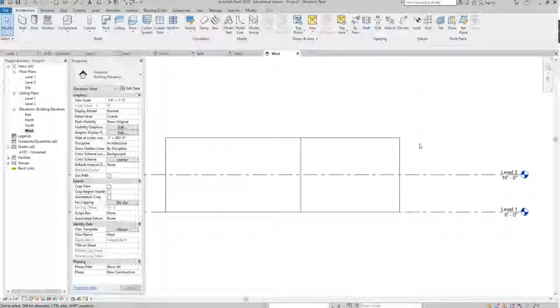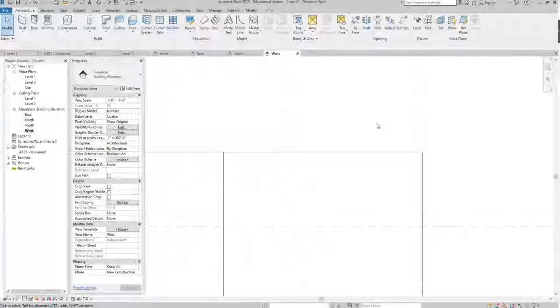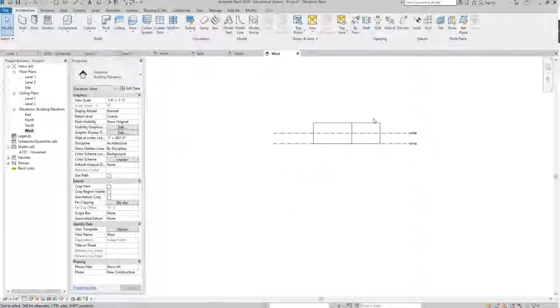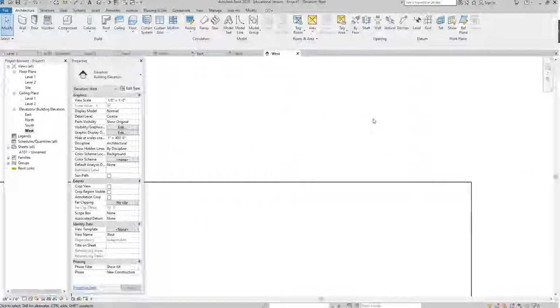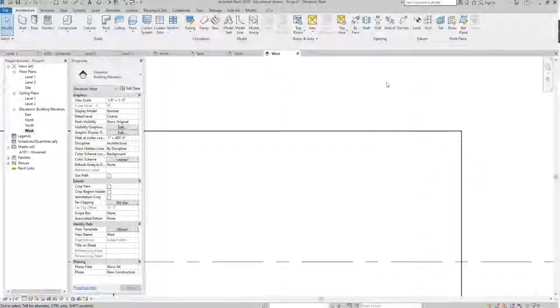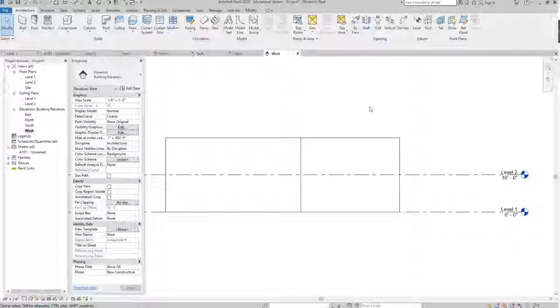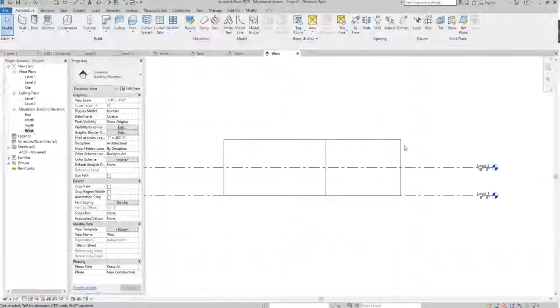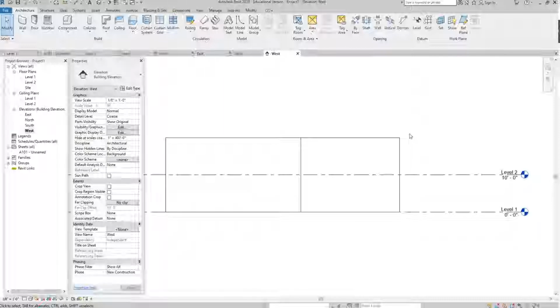So if I want to zoom in Revit, on my mouse, I have a little roller button, right? And if I hover over this white space and I roll my mouse away from me, I zoom in. And if I roll my mouse towards me, the little roller, I zoom out. Okay, so I zoom in, I zoom out. And if I'm zoomed in, for example, but I want to bring the entire drawing back onto my screen, which is called a zoom extent, I double click my roller twice very quickly. Click, click, and it brings me to zoom extents. I zoom in, I zoom out, click the middle button twice, and I zoom extents.